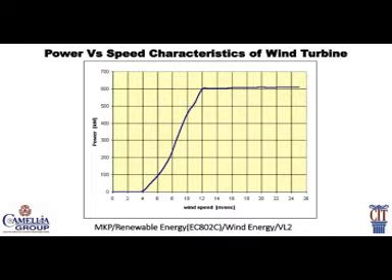Power curves are found by field measurements, where an anemometer is placed on a mast reasonably close to the wind turbine, not on the turbine itself or too close to it, since the turbine rotor may create turbulence and make wind speed measurement unreliable.